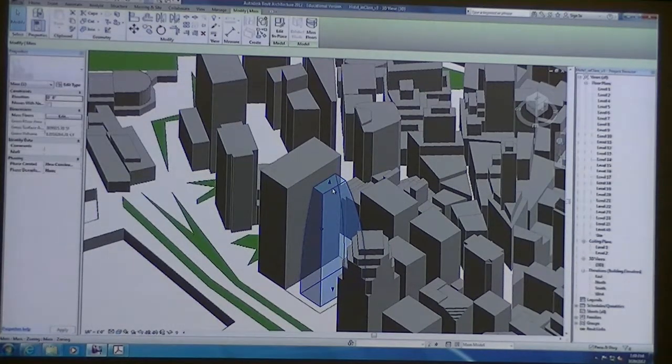Were you still in the unfinished mass whenever you went to the top floor and did the offset of those lines? Yeah. Did you offset these directly? Did you have to trace the outline first? You can just hit offset, and then 61 foot, and then you can hover over those lines. Did they disappear like that? You may have to click into a 3D view and see what's going on. So it's there, it's just for some reason in that view they're going away.